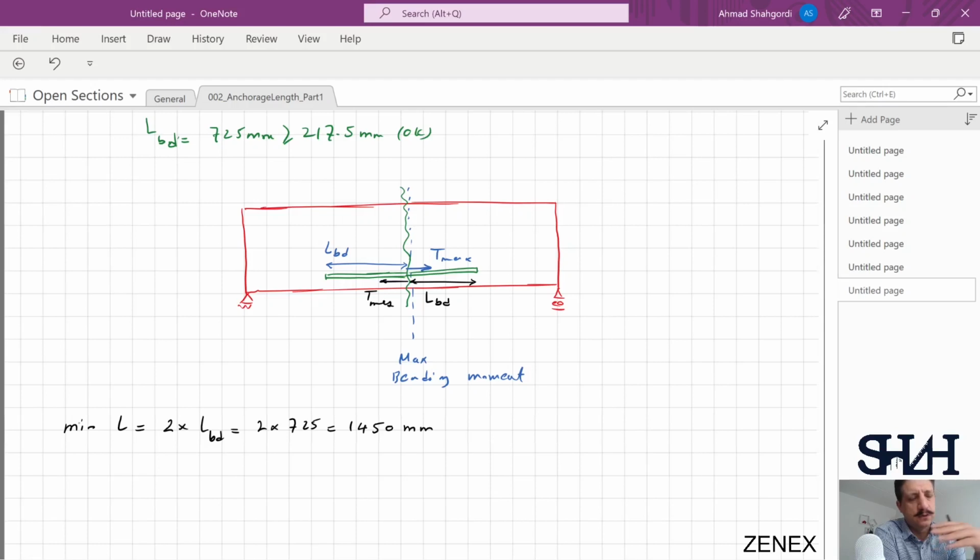Notice that we cannot cut all of the reinforcement. We need to keep some of them to ensure that we have the minimum reinforcement. Back to several years ago, it was important to cut as many as possible if the reinforcement was not needed. But nowadays, at least I can see that there's no cut. One reason is that, for example, here in Finland, the cost of labor work is much higher than the cost of the material. As a result, it is preferred to buy the material.